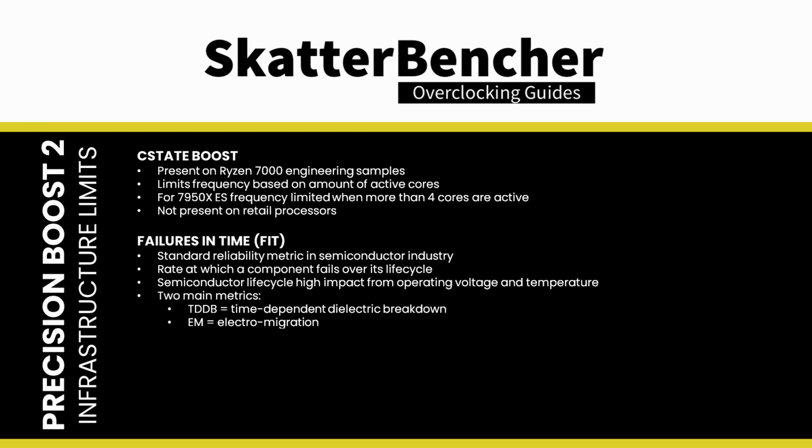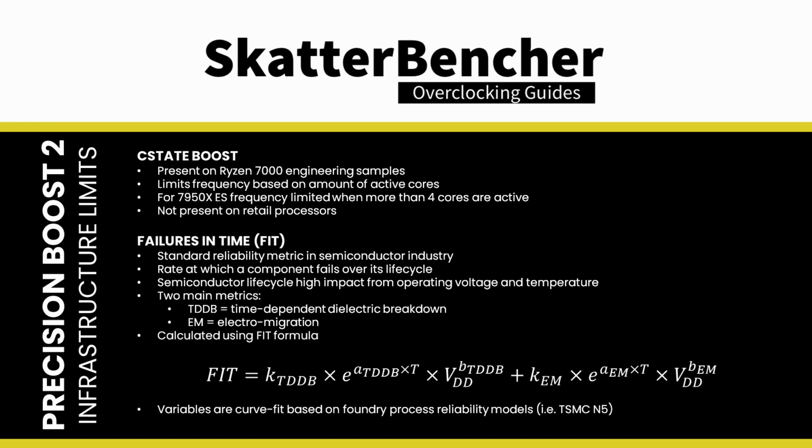AMD's real-time reliability monitoring technology incorporates two critical limiters to long-term reliability in high-performance microprocessors: time-dependent dielectric breakdown, TDDB, and electromigration, or EM. The FIT rate is calculated in a 1 millisecond interval using the following formula. The subscripted variables are curve fit based on the foundry process reliability models. So for Raphael, that's based on the reliability models provided by TSMC.